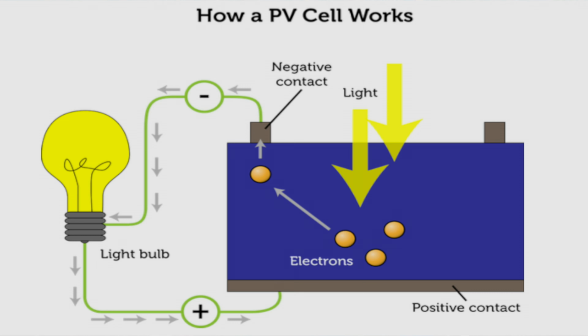What are solar cells? Solar cells convert energy from sunlight to electrical energy. They contain a material such as silicon that absorbs light energy. This frees electrons and creates electron flow, which produces electric current. Solar cells are also called photovoltaic cells because they use light to produce voltage. Contacts in PV cells are like the terminals in a chemical cell. One contact is negative and the other is positive, creating a difference in electrical potential, or voltage, which produces electric current.